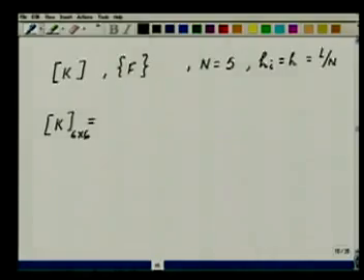This process is called initialization. That is, I set the values to 0. Then I start looping over the elements. See, I'm talking in terms of a computer program. So I start looping over the elements and adding the stiffness entries and the load vector entries from the element to this global K and global F. I'm also going to initialize all the entries of F to 0.